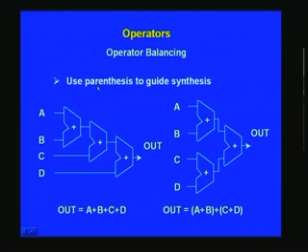We have one more thing before we wind up. Let us say we want to have an arithmetic operation done: a plus b plus c plus d is what we want to compute. If you put this condition here, the synthesis tool will map it like this. It will put 3 adders. A plus b result will be available here, then this will in turn be added with c, and that will appear here and get added in the final last adder, and finally the output will be this.